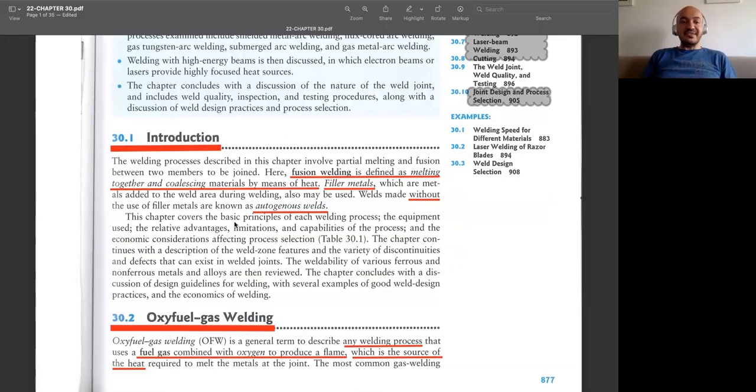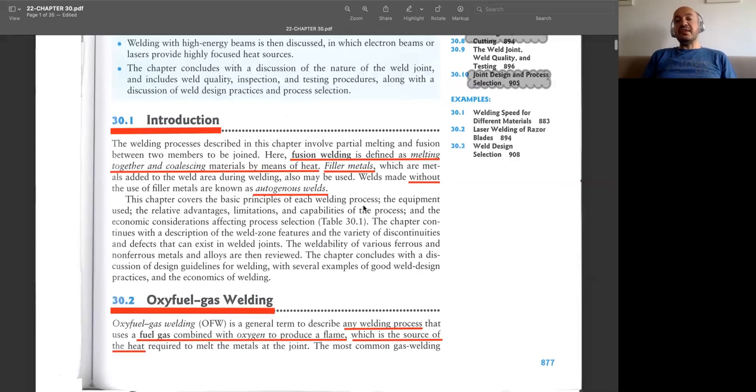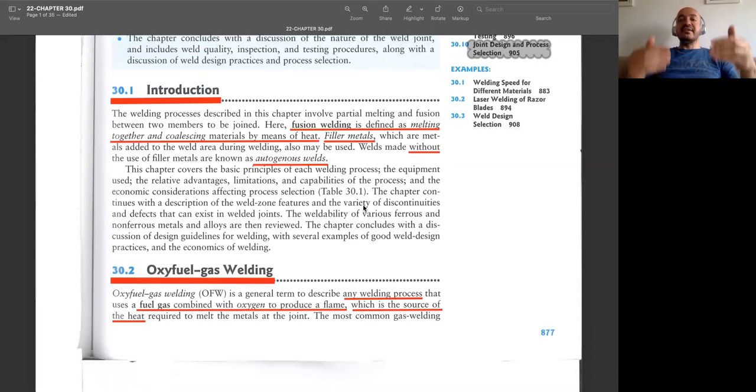For that purpose, we need to melt the materials at the interface. Two regions, two parts, should be melted so that they will be joined in a firm manner and you have stronger bonds between the parts. In some cases, you may need to use extra material so that the gap between the neighboring parts is filled with these compatible metals.